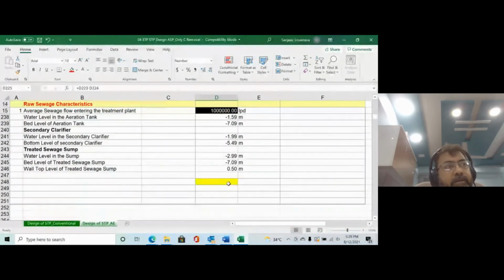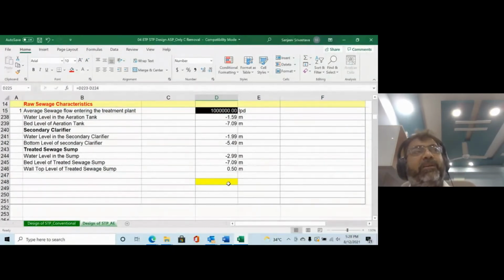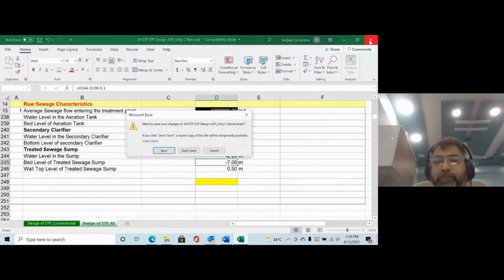And it is okay. This is what the plant hydraulics says. This is the way you will design the plant. Unless you decide there will be a sump and I'll pump it and take everything up. Got my point? When you decide I'll take a sump, I'll take a pump and take everything up. Otherwise, everything will show as negative. It is going to 7.9 negative. So I am closing this file. Just relax a minute.